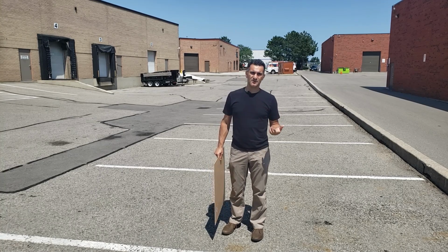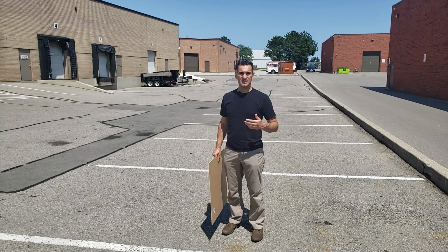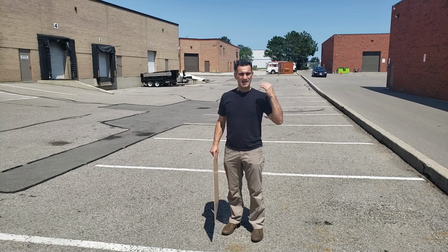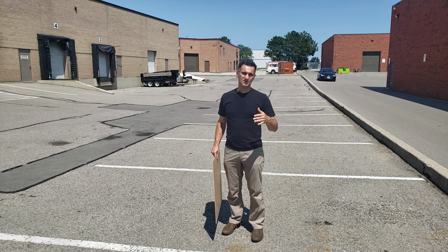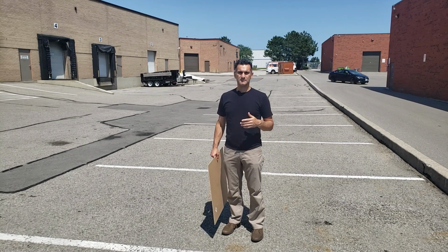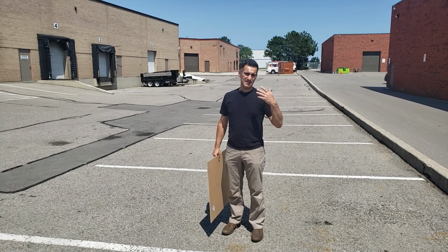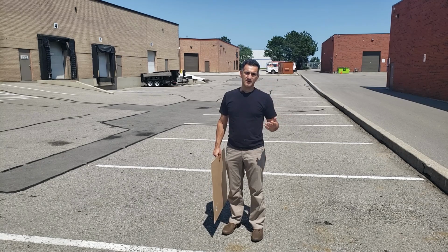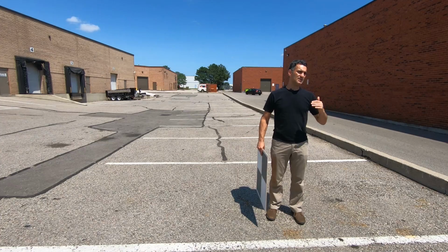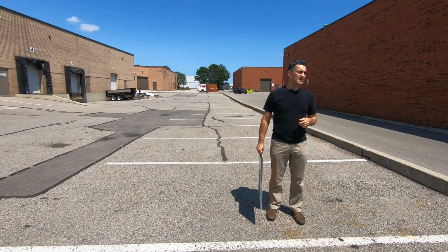But typically, if you're doing photogrammetry, especially for crime scene or crash scene reconstruction, you're not going to be flying at a very, very high altitude. You're going to be at a reasonable height. In some of the previous studies that we've done, we've flown at 20, 40, and 60 meters above the ground, and that seems to be reasonable. And again, you just choose the height you need depending on what you're trying to get at.